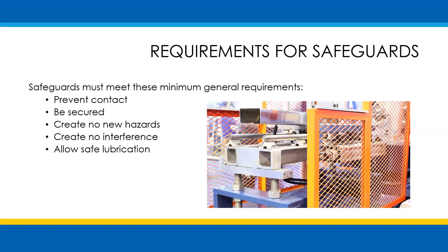The guard should prevent contact between the hazard and a worker. The guard should be firmly secured in place. The guard should create no new hazards or interference on the machine, and it should still allow for safe lubrication of the machinery.